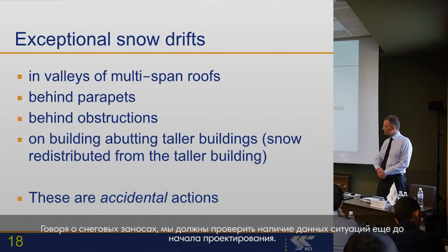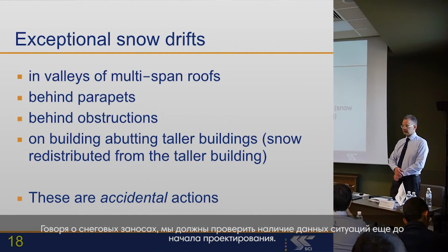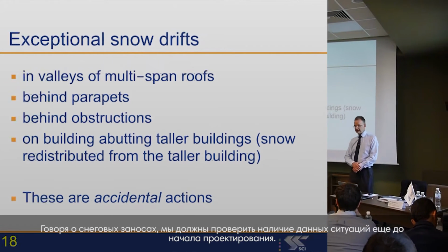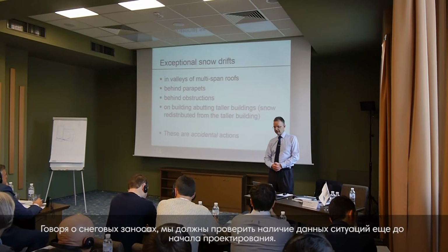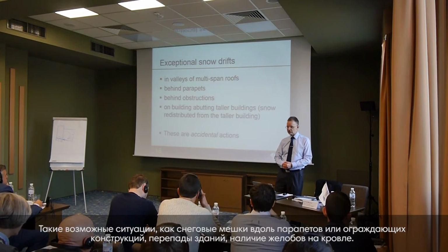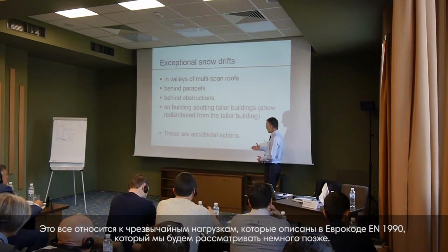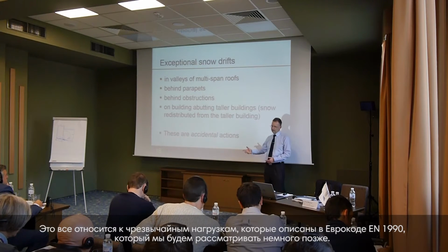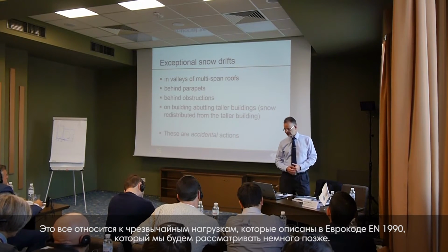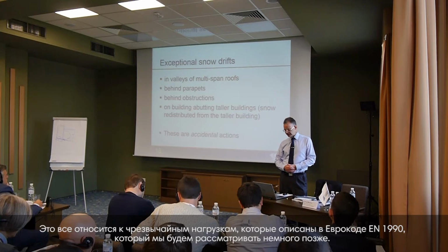I've spoken about snow drifting. This will be a key design case for you to check, so in valleys, behind parapets, behind obstructions. But remember, there are special rules in EN 1990 to deal with accidental actions, which we will see a little bit later on.